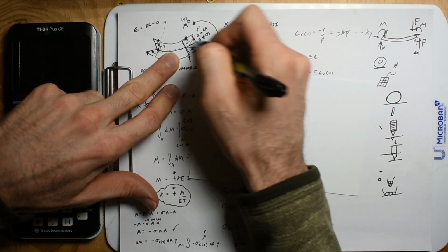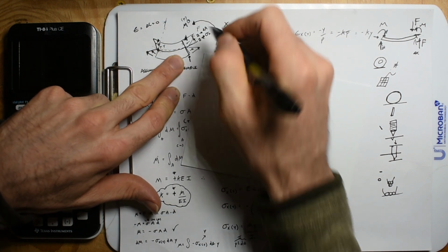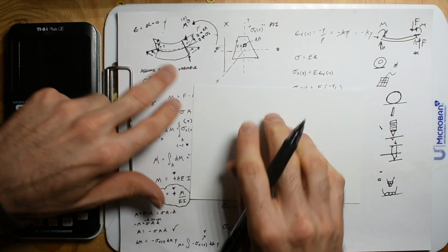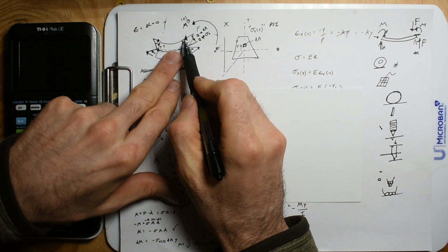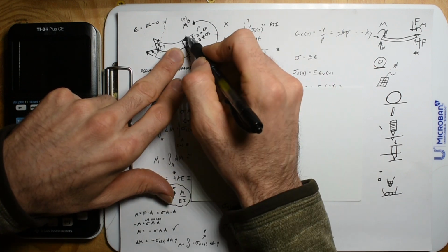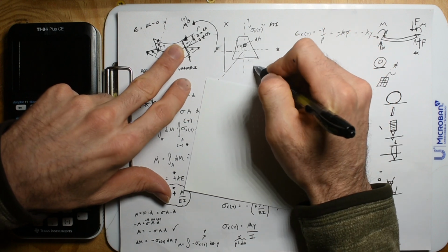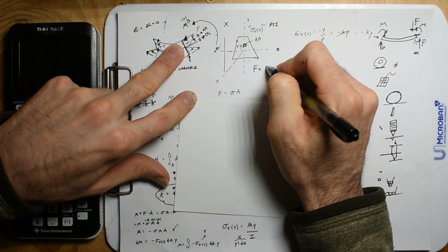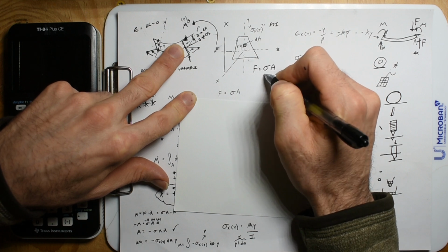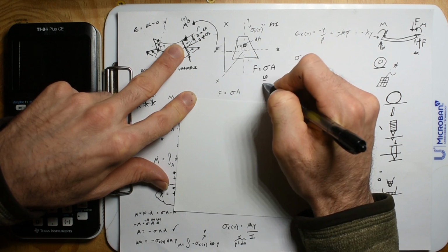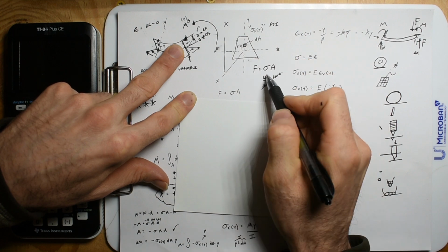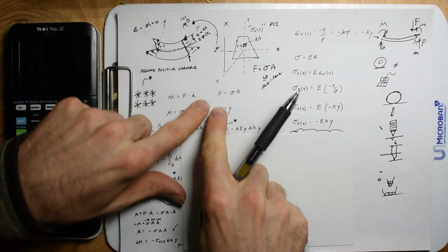So this is the x direction, upward is the y direction, and we're going to turn this face sideways. That means we have forces on this face, and the forces on this face are going to be the pressure times the area. Pressure is in pounds per inch squared, area is in inches squared, and those give us a force. So that's what I would have right here.